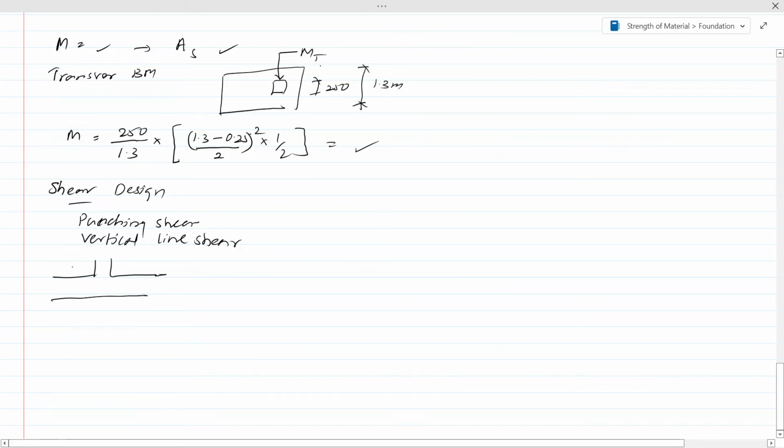So you know the d distance, we have to calculate the effective depth. D is effective depth. Here we have to find the V. Since you know the V here, shear stress can be calculated by V divided by b into d. B you know the width, d is effective depth. From that you have to calculate the v.